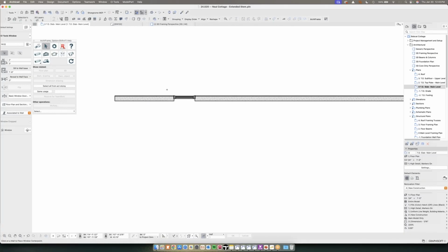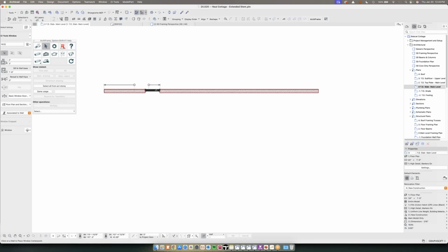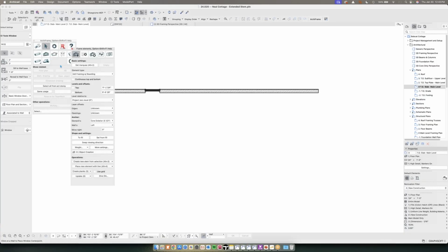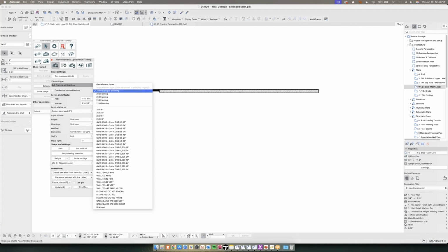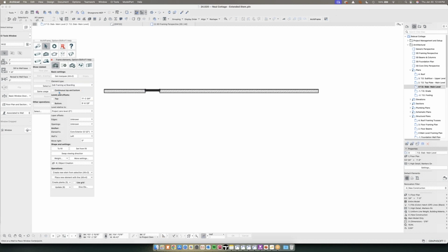So in terms of detailing this wall out, it's a two-step process. Step one is you create what's actually called the ArchiFrame element. So it's the element that the framing gets attached to. For example, in this one here, I can create different layer types for the different type of wall framing I want to do. So 2x6, 2x4, 2x8, 2x10. So I'll do this element here, for example, 2x6 framing with boarding.